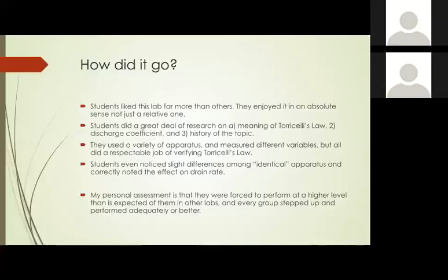It turns out I'd taken two of the apparatus and turned the orifice upside down on two of them and had it right side up on the other. So we had a very sharp weir on one and a funnel-like weir on the other, which gave them different discharge geometries, and so a completely different discharge coefficient. The students, comparing their data with other students, said, golly, we're using the same apparatus, but we're getting such different results. They investigated, found the difference, and then explained it on the basis of what they observed.